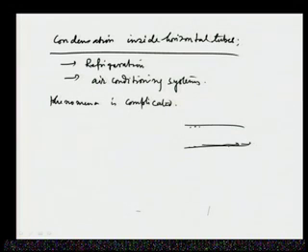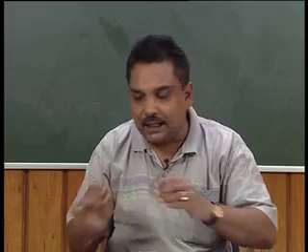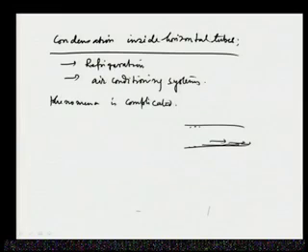That is a kind of, we can think of it sometimes as an open channel flow of the liquid. So this condensate moves through an open channel, because above this liquid it is full of only vapors. Some of the vapors are getting condensed and coming down to the bottom due to gravity, and then they are flowing like this. So this is an open channel flow kind of thing.